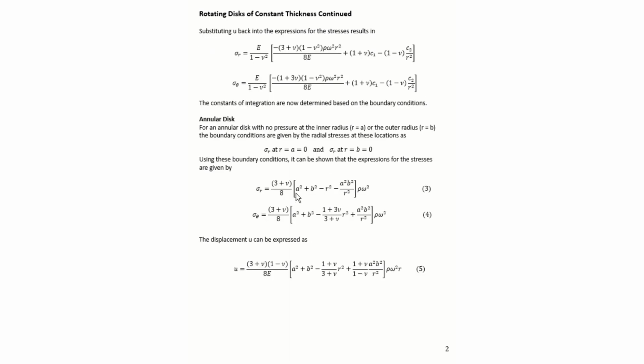Applying these boundary conditions, we can solve equations 6, 7, and 8 for the radial and circumferential stress equations and the displacement equations. And you can see here that these expressions for the solid disk are simpler than these equations back here for the annular disk.